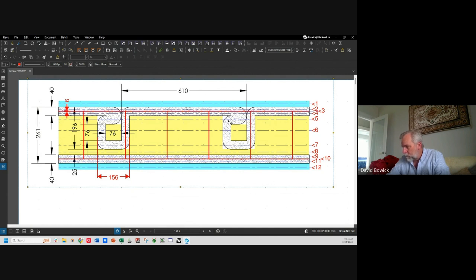Then we have a layer through this portion where it's back printed to create this core. Little sidebar here. The 40 millimeters of 3D printed concrete has no effective structural capacity. It's much too slender, so we need to introduce a core. The core has a hollow part in it that allows us to put reinforcing in if we need it. So we back print here parallel to the inside face, and so that's a layer. Then there's the layer through the center of the core. Then there's the layer through the inside face shell.